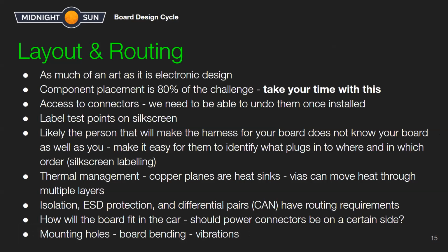So ideally with that, you want to start with just showing the rat's nest and all the nets going between the components, and try and make that as neat as possible. That's how I do it to start off. That's a good way to approach it. Obviously, there are different methods that work for everyone, but trying to make the net list as neat as possible, and then moving on to routing. The routing is super easy if the net list is already straight lines from component to component and not crossing too much.